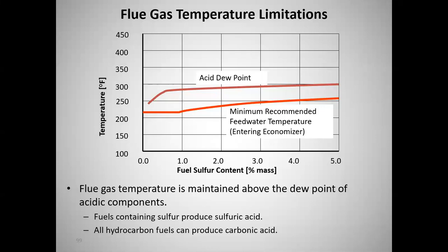And the reason, of course, is the colder water you put in, right there where it first comes in, that's where it's going to condense, because that's the coldest water hitting that temperature of flue gas. Then as the water goes on through the heat exchanger, it warms up, and so the flue gases in that portion are probably not going to get quite as cold. But locally is where you're concerned about the local cooling at any one point, because that's where that acid will start to condense and collect.